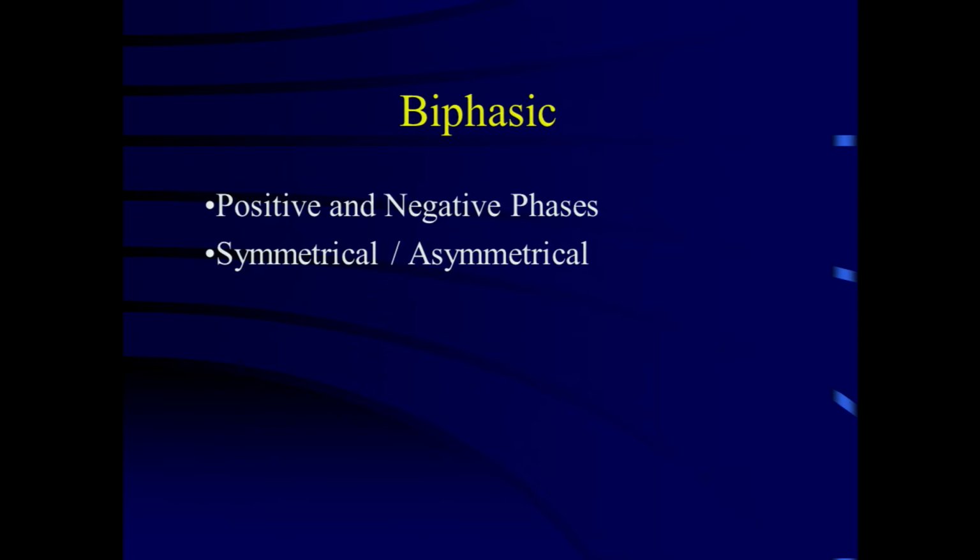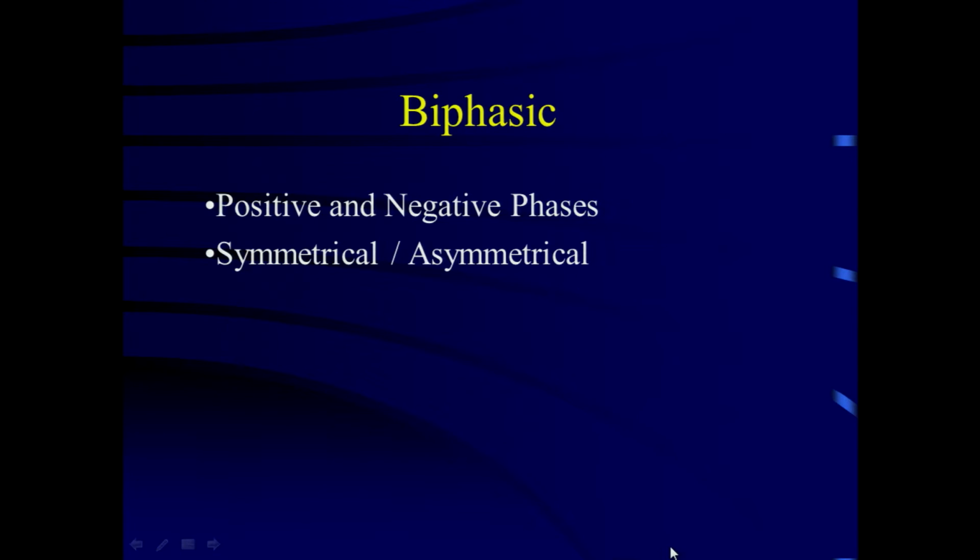You know, how do you measure pulse? What do I care, where do you measure? I apply the pulse, I get cured, I walk. At the end of this course, they should be able to measure. They should be, not me, you all better learn, not me. That is a good point, but it is 10 to 90 normally, the default is 10 to 90, everybody knows, because we cannot know the beginning of the pulse, end of the pulse. So we start from 10% of the magnitude up to 90% of the magnitude.